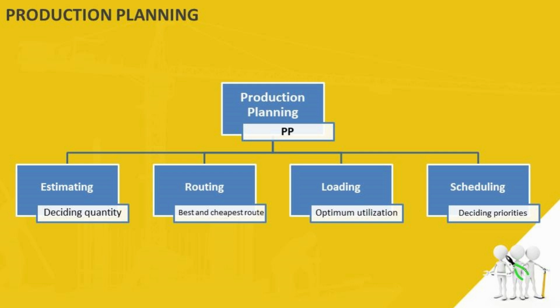See, in continuous manufacturing processes that we have discussed earlier, like in a cement industry or food industry, the routing function is built in with the original design of the plant and sequencing of machines. However, it is a major planning activity in the case of intermittent production, which is particularly in customer oriented products. Routing can be generalized or detailed. Generalized routes are established by workstations or workshops, whereas detailed routes are incorporated within a workstation for different work centers or machines.